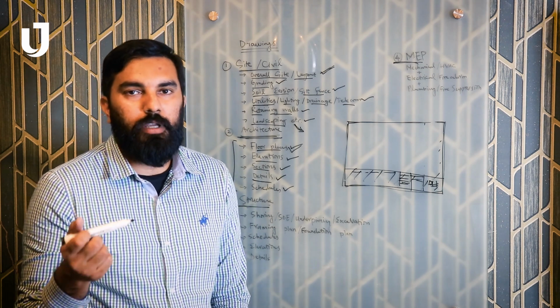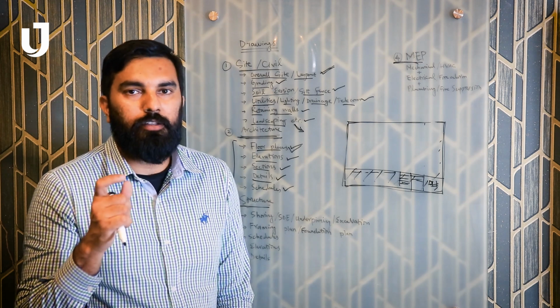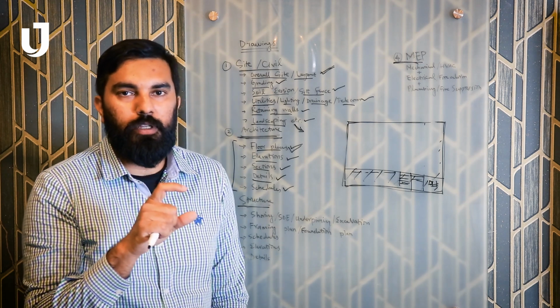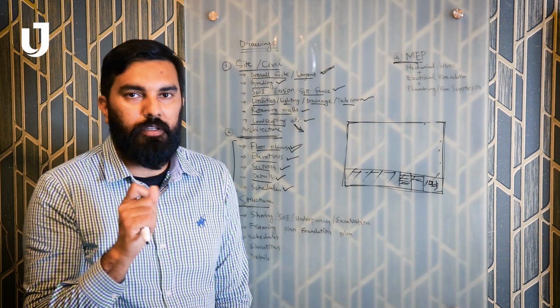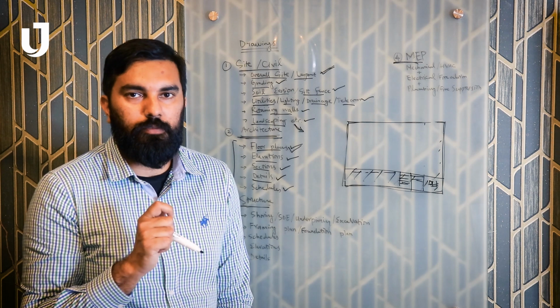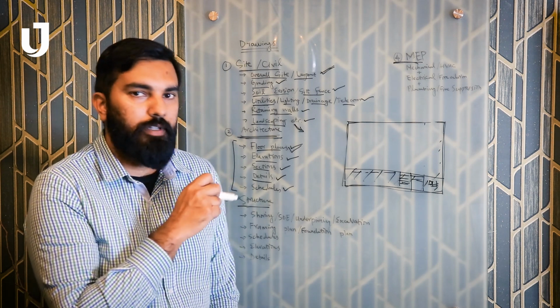Sometimes the project is so big that you have to prepare additional details apart from the sections. Like the blow-up plans, you have to zoom in for the lintel details, the sill details, and the flooring and ceiling details. So in those drawings, the detailed drawings, we're going to be having the details for these areas.